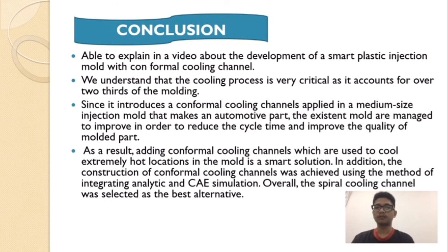Furthermore, for the third point, since conformal cooling channels were introduced in a medium-sized injection mold that makes an automotive part, the existing mold managed to be improved in order to reduce the cycle time and improve the quality of the molded part. As a result, adding conformal cooling channels to cool extremely hot locations in the mold is a very smart solution.